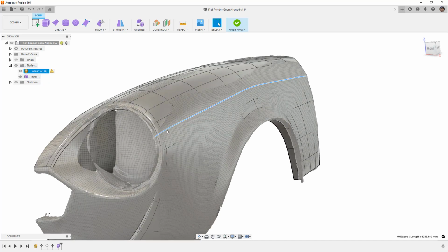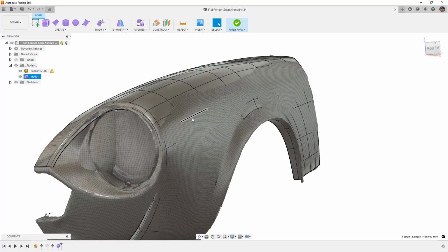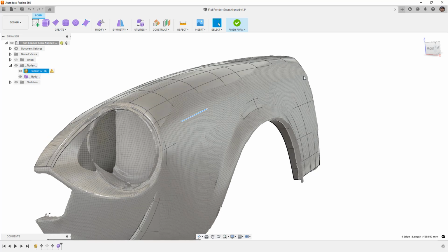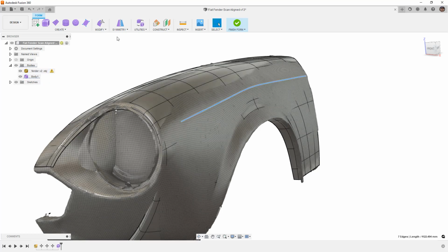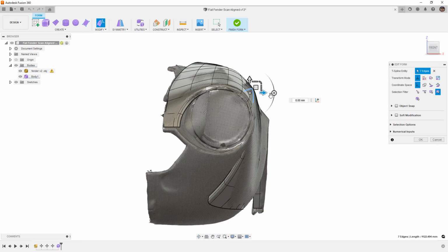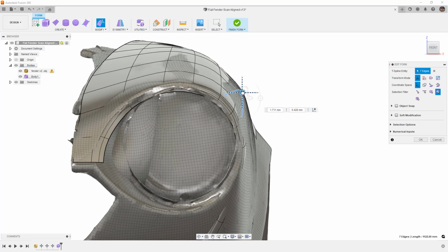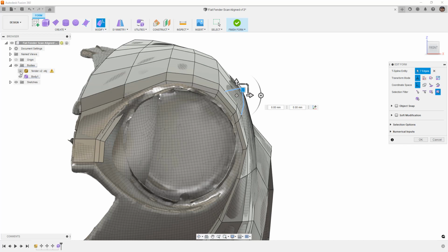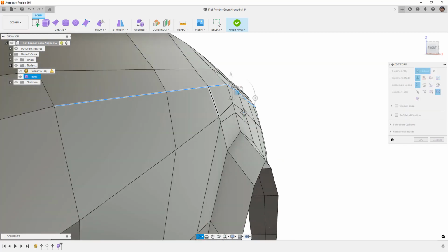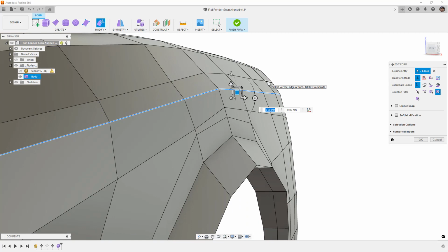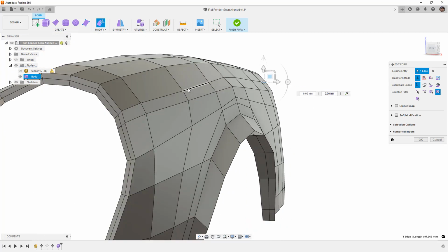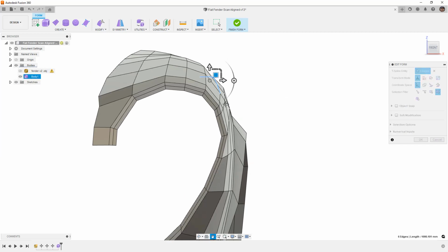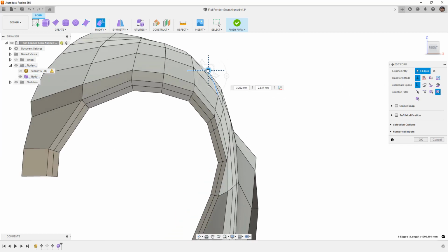If it's okay at the headlight, but it's not okay everywhere else, what I'm going to do is select just past that, so here, and then find that other edge, shift double click, and then I can go to Modify and just pull that whole edge out a little bit and change the shape of the fender. Good idea while that's selected to hide the mesh and also show the box display. And then likely what we're going to have to do is the same thing here, shift double click. This one, instead of just going out, is probably going to have to go up a little bit.